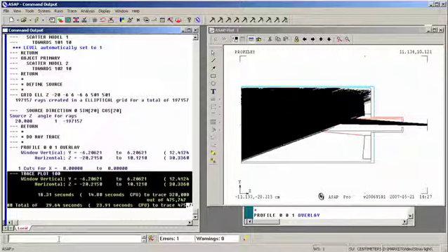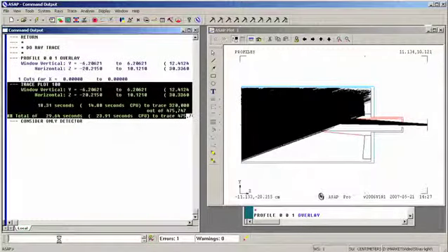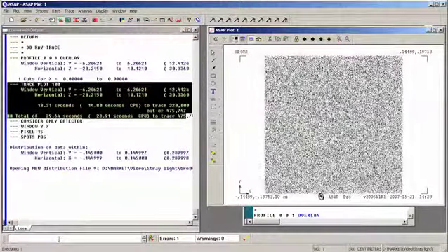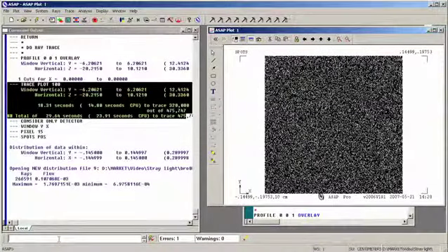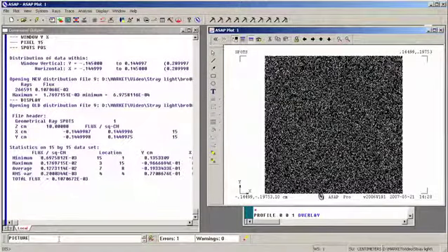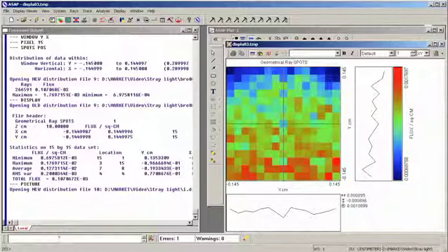Okay, we can now do exactly as we did before to calculate what the stray light irradiance is. Consider only detector, window YX, that's the size or dimensions or axes of our window. Pixel 15 is the resolution of our plot. Spot's position gives us our spot diagram and also calculates the stray light irradiance. Display command reads the file, and the picture command makes a picture of it. And so this is our stray light irradiance on the detector.